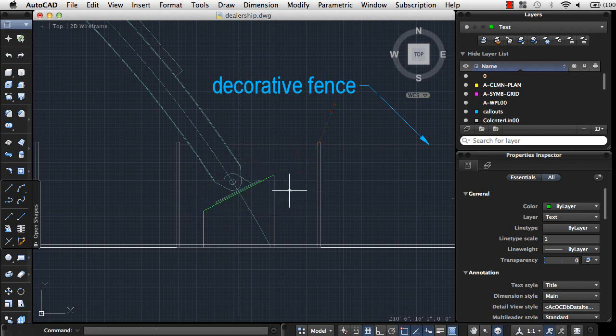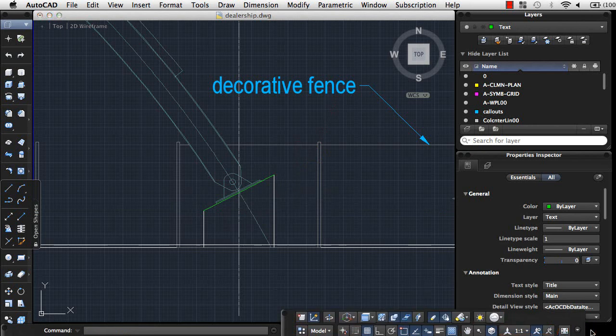To the right of the command line is the status bar. The status bar displays layout and view tools, common drafting aids, and annotation scaling tools. Click the disclosure triangle on the right side of the status bar to access the 3D status bar. Here you'll find 3D object selection and manipulation tools and common lighting tools.